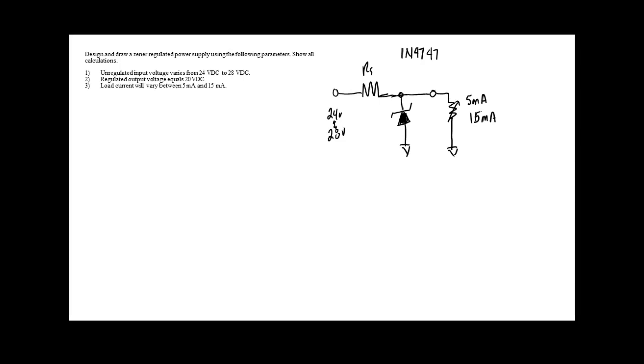20 volt VZ. So we look in the VZ column and find one that says 20 volts. And then we're probably going to use an A because we want a 5%. And then we're looking up IZK. What's IZK for 4747? Okay, but we wouldn't say 0.25. What would that be? Just move it 3 places. 250 microamps. Just move it 3 places to the right and go to the next unit, right?